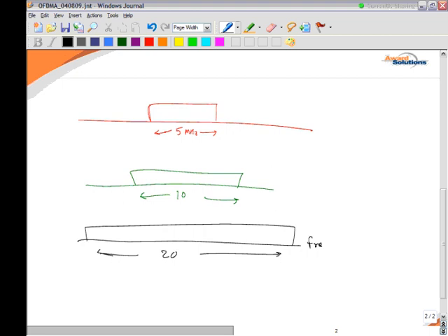So this is all frequency. If I have 20 megahertz spectrum, I would have 1200 subcarriers, and the spacing is always 15 kilohertz. The subcarrier spacing is 1 divided by the modulation symbol period.